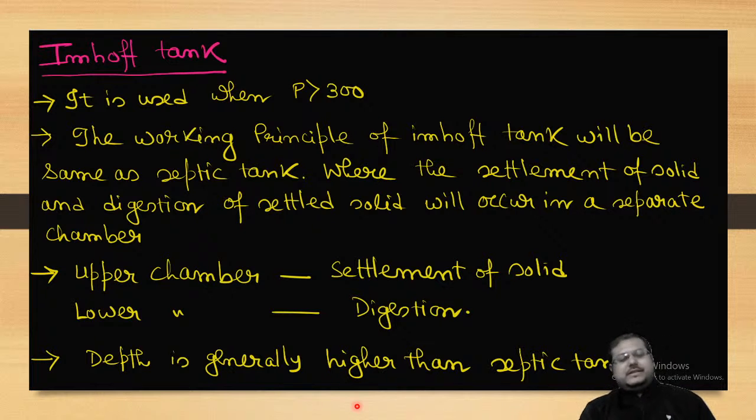There will be two separate chambers, but the concept is the same. In the upper chamber there will be settlement of solids, and in the lower chamber there will be digestion of settled solids. And the depth is generally higher than the septic tank. Generally it is obsolete nowadays. Instead of putting an Imhoff tank, n number of septic tanks is preferred. Just have a look.